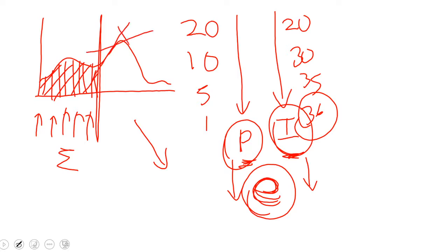Normally we get the tangent of the graph, and that is the rate of change, how quickly it has changed. So with derivation, we don't see the integration part or the proportional part, we see how quickly something is changing. If it is changing quickly, then the effect will also be applied quickly. If it is changing slowly, the effect will also be applied slowly.